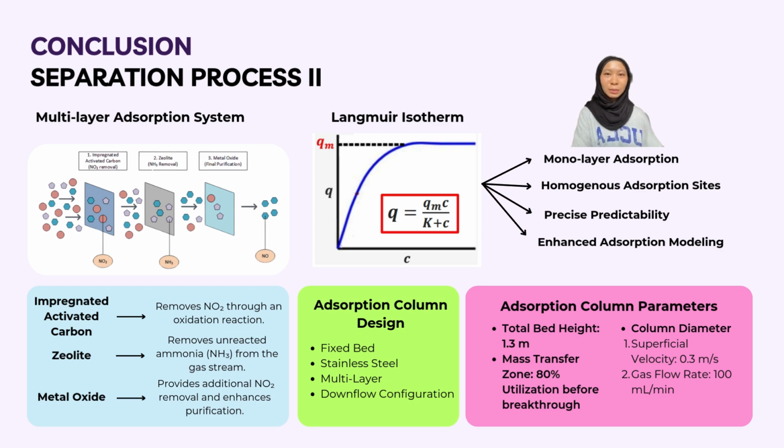Additionally, the Langmuir isotherm offers precise predictability in adsorption studies. It allows us to accurately determine adsorption capacity and model breakthrough curves, which are crucial for designing an efficient adsorption column in gas purification processes.